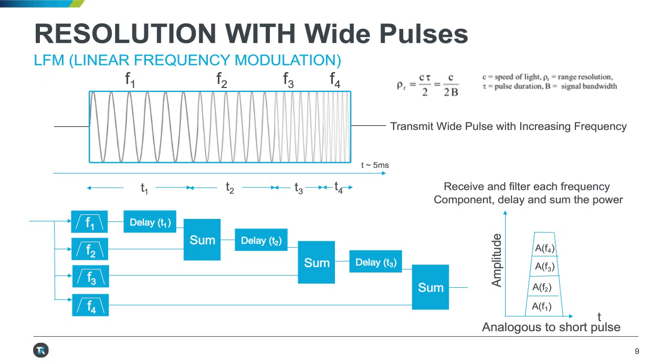So this is key, linear frequency modulation, called a chirp, of course, because if you would listen to it, and many electronic warfare officers would listen to chirps during the Cold War, because you could identify the threat, the radar that's tracking you and ultimately connected to the missile system that's going to shoot you down. You could identify that by listening to the sound of the frequency modulation, and it would sound like a bird chirping.